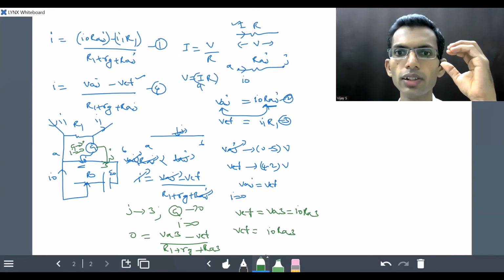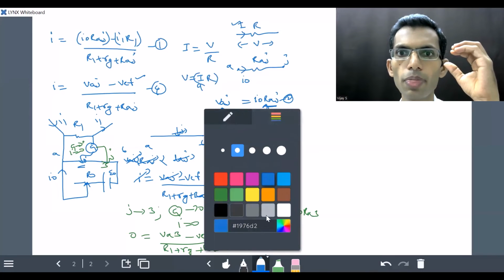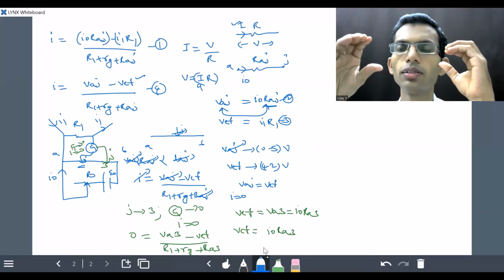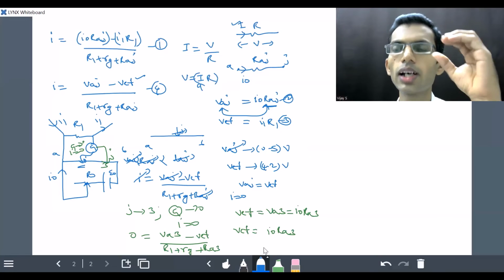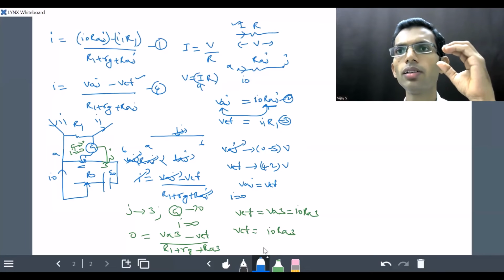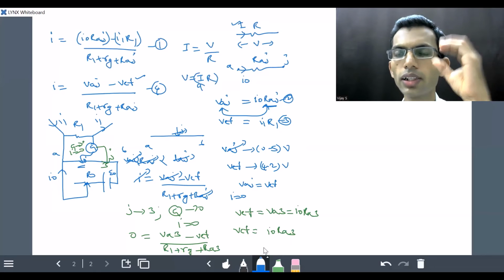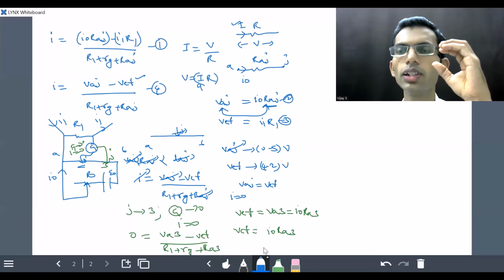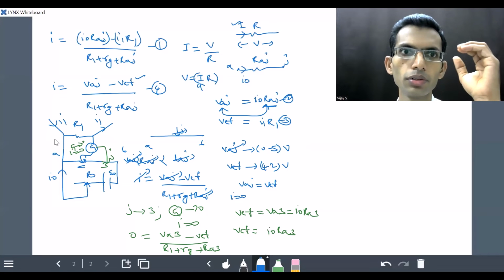But the standard practice is to replace the resistance R1 with a standard cell and obtain the zero deflection of the galvanometer. At that condition, we can obtain the EMF of the standard cell in terms of circuit parameters, just like I0 and the resistance of the wire. So in the standard practice, the resistance is replaced with a standard cell like this.